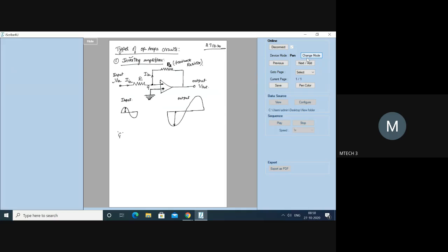What is G called? G is called the summing junction or virtual ground point. Now this is going to be your I out, and this is the V out. So the feedback has been taken from the output through the resistor R2, and it joins at this point called G.